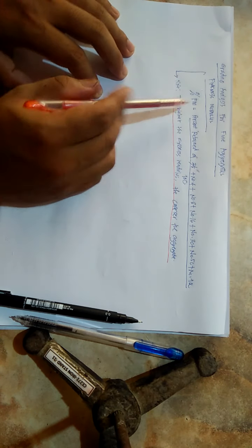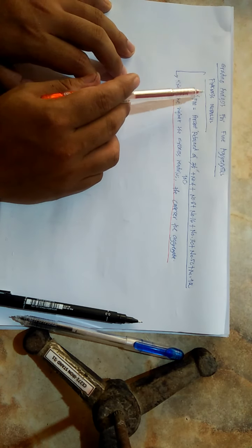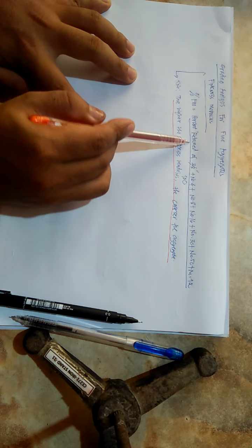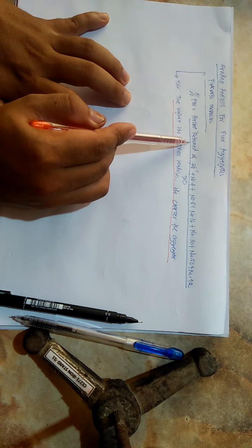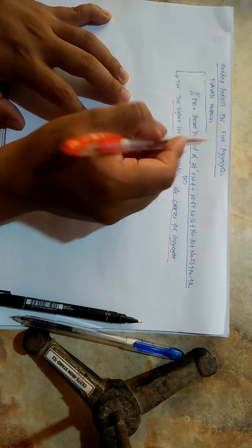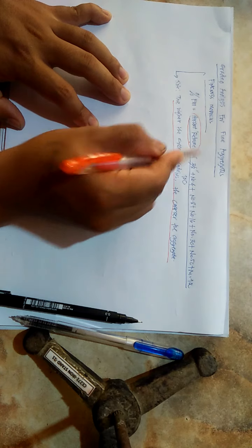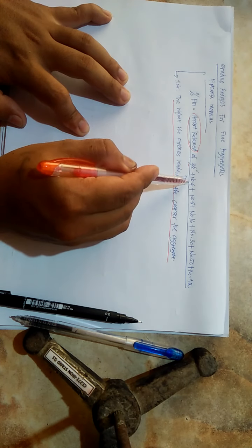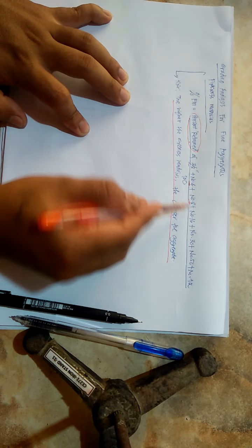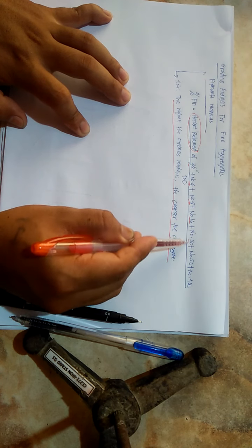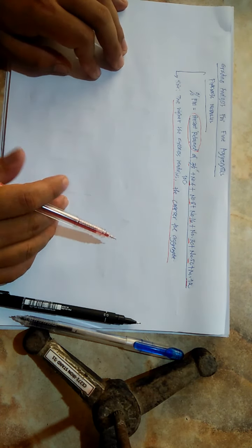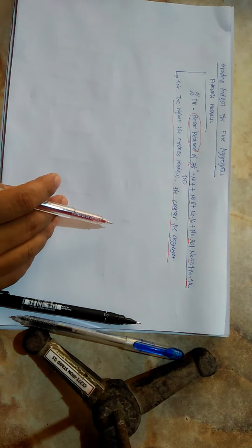Again, just to review the formula for your fineness modulus, it states here that your fineness modulus is equal to percent retained. Always take note, guys, percent retained dyan. Hindi siya percent passing. So, percent retained of what? Sieves. Set of sieves which are composed of 3/8 inch plus sieve number 4 plus sieve number 8 plus sieve number 16 plus sieve number 30 plus sieve number 50 and plus sieve number 100. Okay, that would be your fineness modulus.